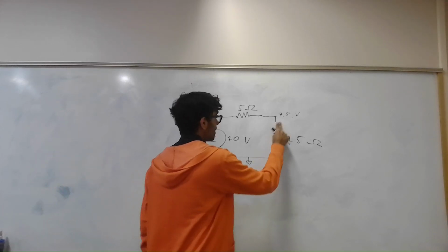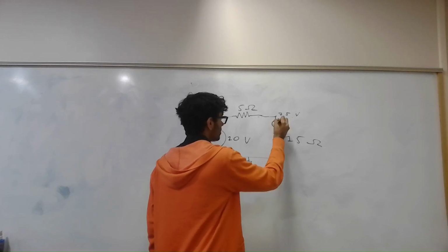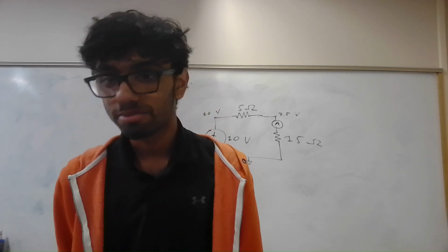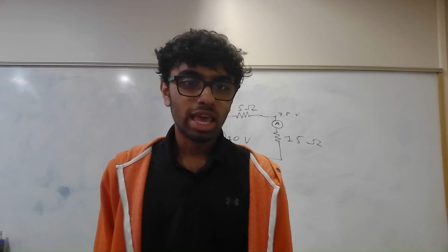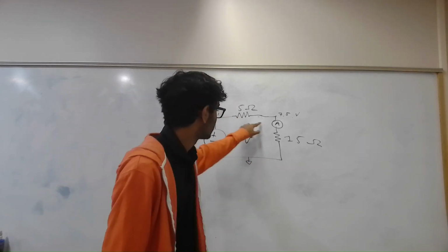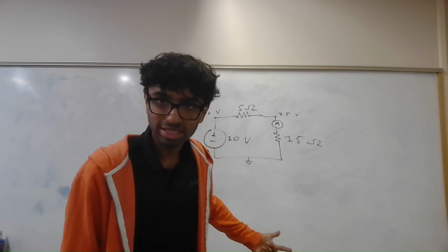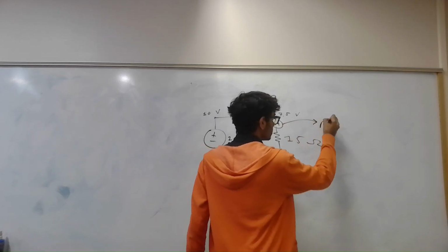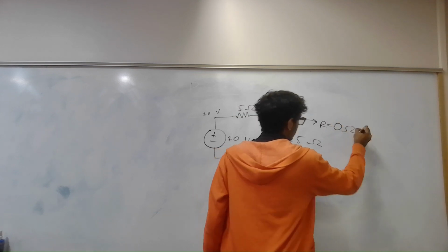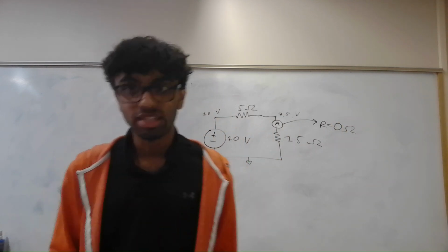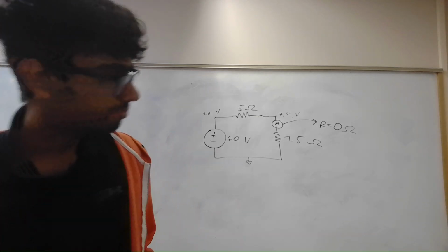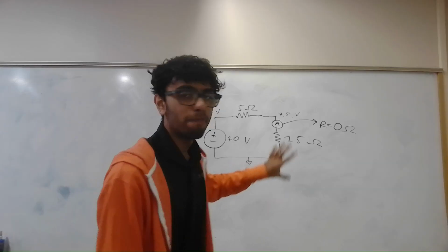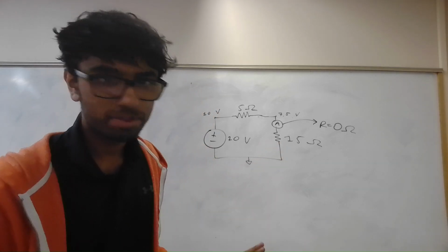So my ammeter, I'm going to symbolize it with an A. That's for amps, the unit of current, and A is for ammeter. And I'm going to have this device be put, we call it in series, with these other components. This device has a resistance of 0 ohms, or something very, very close to 0 ohms. In lab, this is basically how it works. And what it does is it measures the current without messing with anything that's going on in the circuit.